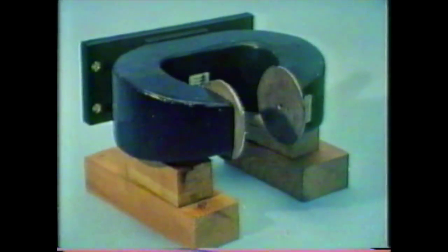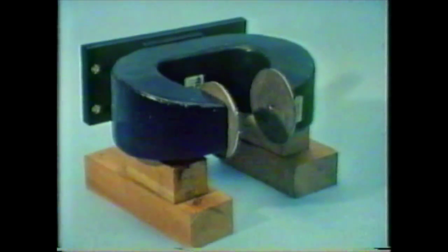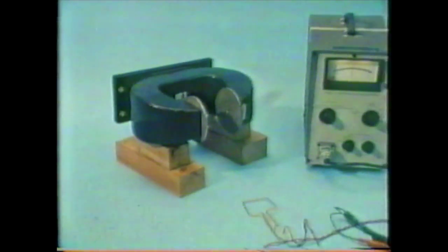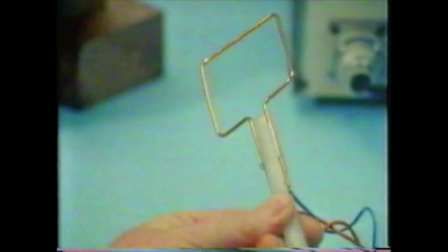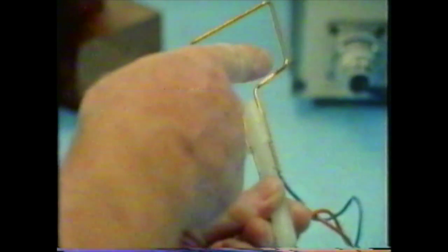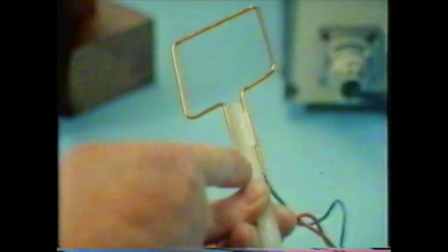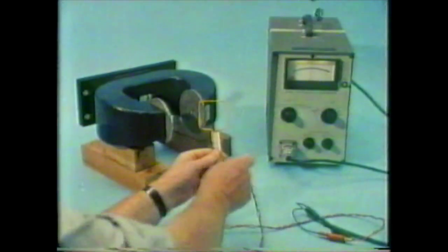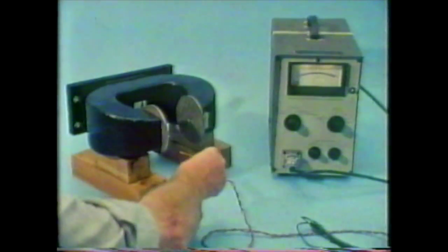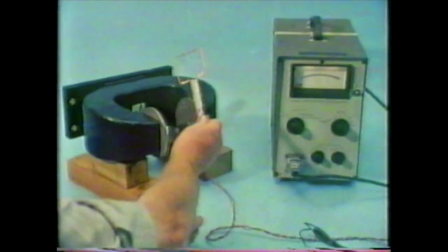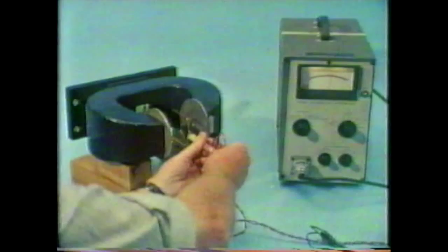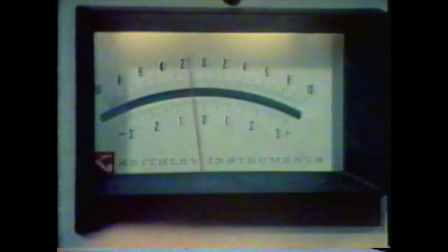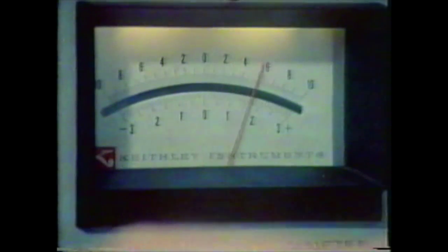Here's another magnet, a permanent magnet, like the one we've just used, but a different shape. We're going to make up a simple electrical generator using this magnet and this single turn of copper wire. It's fixed on an insulating handle and connected to the galvanometer. If we just move it around between the poles of the magnet, again a current passes through the copper wire just as long as it's moving. If we rotate it like this, we get an alternating current, which changes its direction, first flowing one way, then the other, as the coil's rotated.